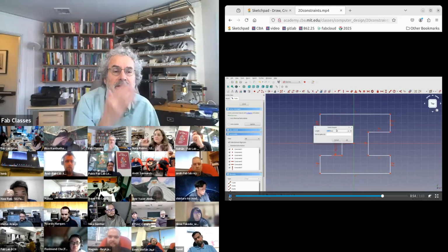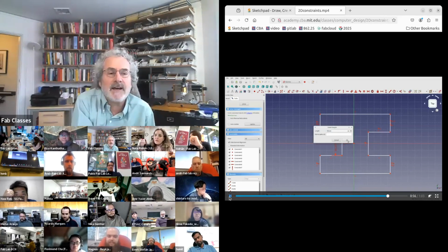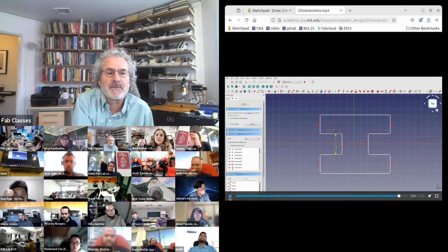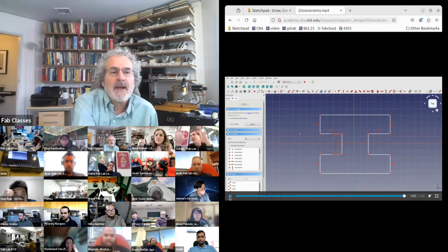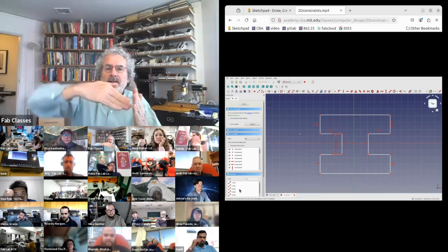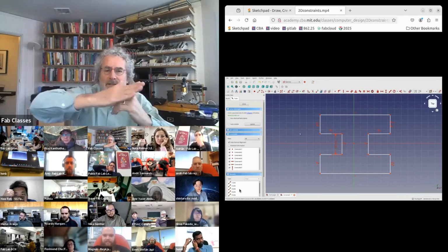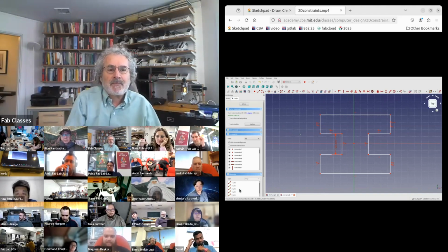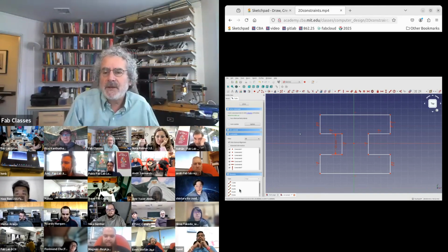Then I'll pick a dimension constraint. I'll give that one a size. And if I set that size, everything adjusts around it. And so there's constraints to be parallel, perpendicular, fix an angle, tangent, aligned, distributed.